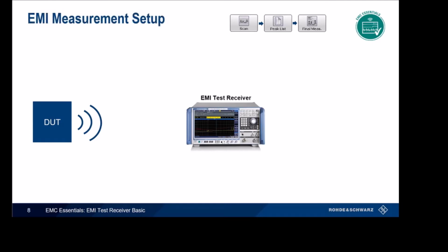Our setup is looking closer to an EMI measurement setup, but we still have a few items to add. Let's start with radiated emissions, which is often referred to as RE testing. As the name implies, the measurement of this energy is radiated or emitted into the air. To receive the measured power emitted from the device, we need to add an antenna to the EMI receiver. The radio and printer example from earlier was a radiated emission setup.